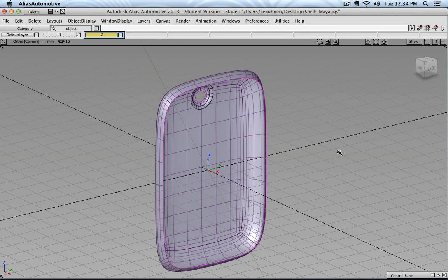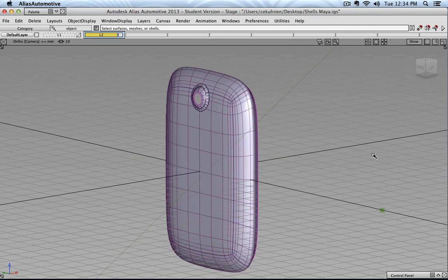One tip, however, if you want to print something, and that is the most important lesson, always make sure your Alias model you build in a good way, don't have surface kinks or bad geometry inside your NURBS model, because that will always be continued inside your polygon mesh export and will give you a lot of headache afterwards. So as long as you really try to work clean in Alias or Blender, then your rapid prototyping mesh will reflect that and you won't have any issue with it.